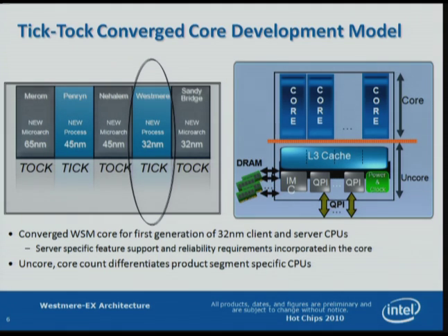If you look at the different product lines, specifically across client and server CPUs, they leverage the Converged core, but they differentiate themselves by instantiating a different number of cores, and also in what we call the uncore, which essentially comprises the last level cache, your quick path interconnect, system interconnect, and your memory controller, and a few other miscellaneous functions like power and clock control.